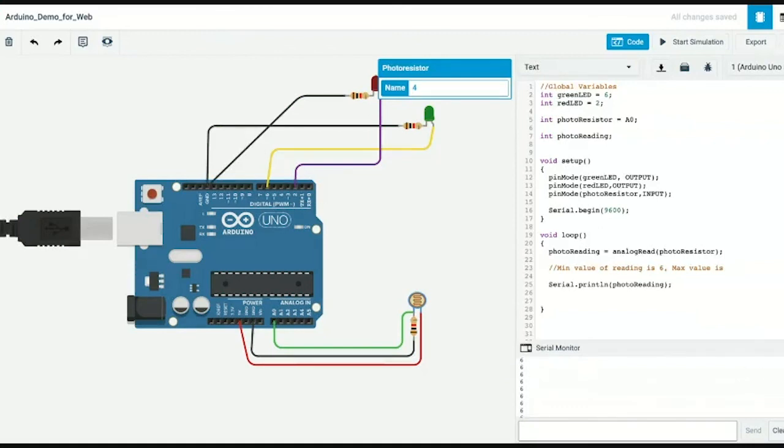What's great about this serial monitor is that it tracks all of the data, and we can scroll up to find the maximum value. In this case, this max value is 679. So we have the information that we need to know the minimum and the maximum working values that we can use, but we want to create interactivity not only when it is 100% bright or 100% dark, but in between these two values.